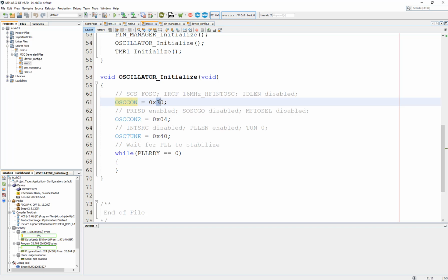And this hex number, why is it a hex number? First, it's easier to manage. You don't want to type every single bit for 16 bits. Just two hex digits will cover 8 binary bits, or 1 byte, right?